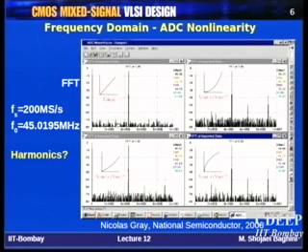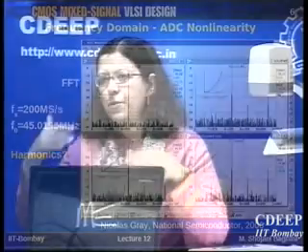And in fact, that will be exactly 20 log of 1 upon M over 2, of course, because the FFT also takes half of the number of points. So exactly 20 log of 1 upon M by 2 will be the shift in the level of signal power that you will see here. You just check it and confirm how much difference you get. That depends on the number of samples.